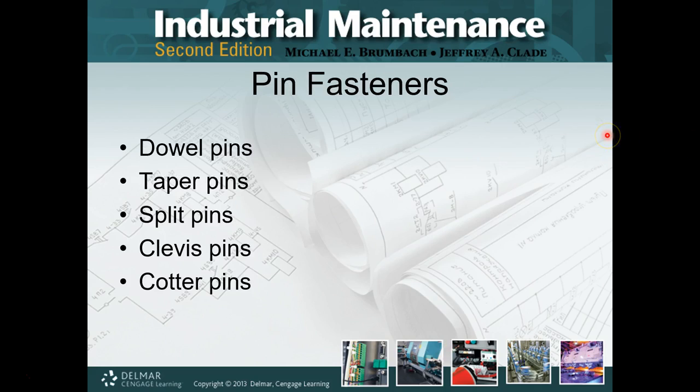Pin fasteners: dowel pins, taper pins, split pins, clevis, cotter. They have really great examples on the pages and in the book and whatnot. I gave you a couple of ones as well. Dowel pins are nothing more than a means of guiding and what they call registering the parts of 2 casings together. All right, so all these are positioning pins, and that's it. They don't really serve as a true fastener. I mean, they don't add any strength to the component.